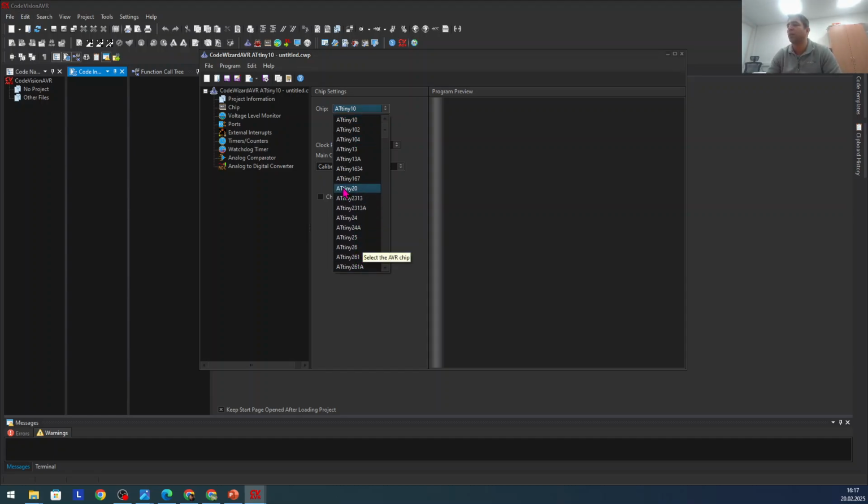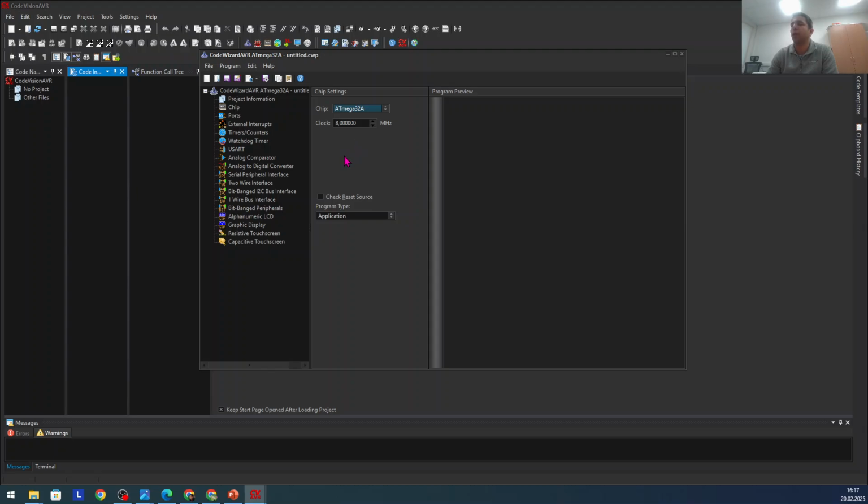Basically, I can just set the ports to be output and pull up the push buttons, and then it will be done. But for the second method, which is with the timer, I have to set timer 1, and timer 0, and for the automatic 100% using timer for making pulse width modulation, I should make the timer 1 setup.